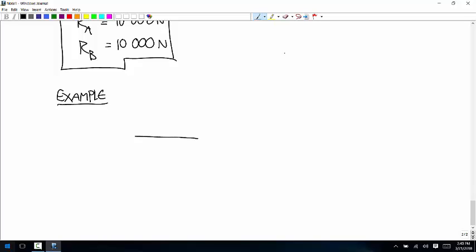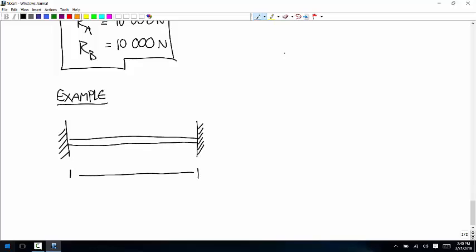Okay, so let's say that you have a bar that has a length of 5 meters. And it was built at 30 degrees Celsius. And we have to account for the fact that it's going to get down to negative 30 degrees Celsius. Okay, so the change in temperature is going to be equal to negative 60 degrees Celsius.